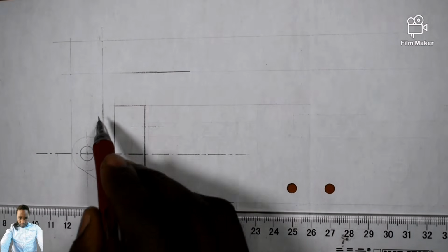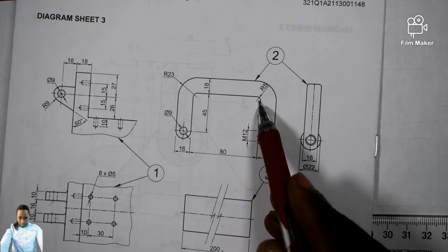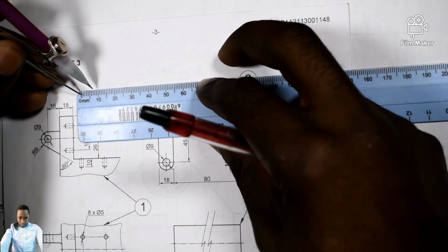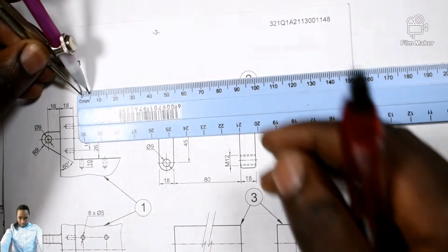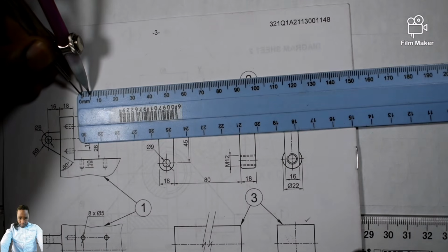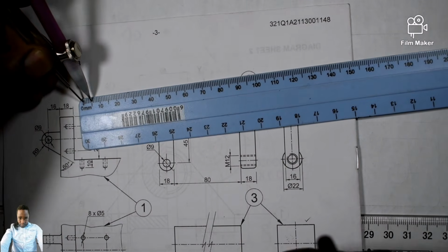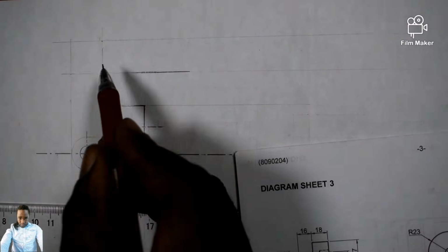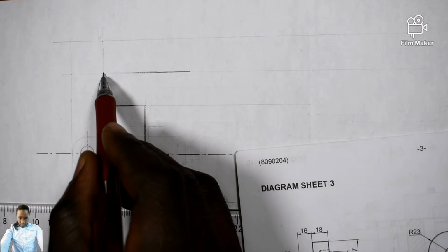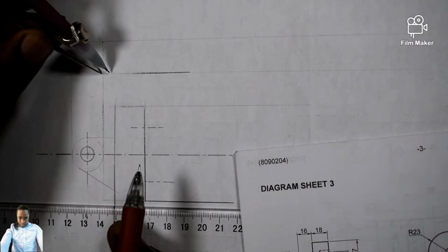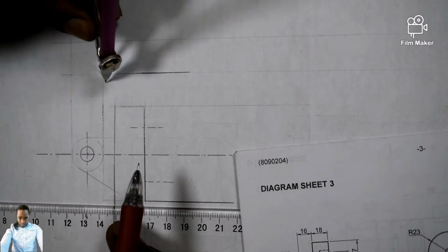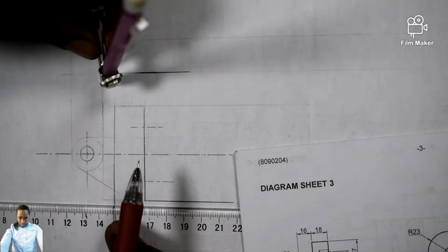Right, so I didn't draw dark till here, because check this, the set is radius 5. So I'll simply open my drawing compass to 5 millimeter, something small, 5 millimeter, isn't it? This is 5 millimeter. So I come, I just place it where these two are perpendicular to each other. I mark this side and I mark this side.